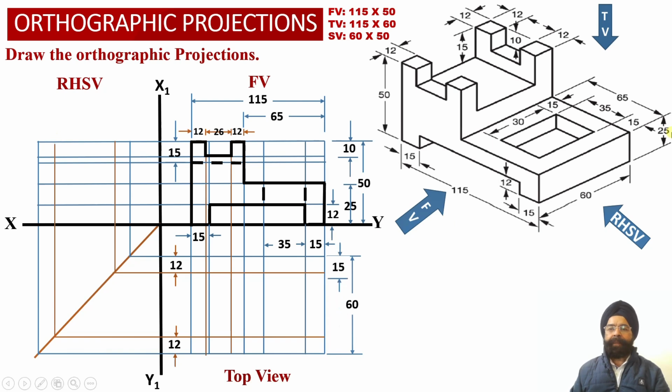Next we know that corresponding to this rectangular slot, we have been provided with the information that the total depth of element number 1 is 60 millimeter, while this slot, having dimensions 30 millimeter by 35 millimeter, has been located centrally on the top surface of element number 1.